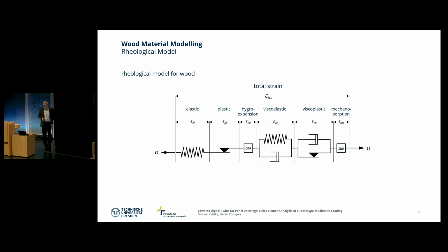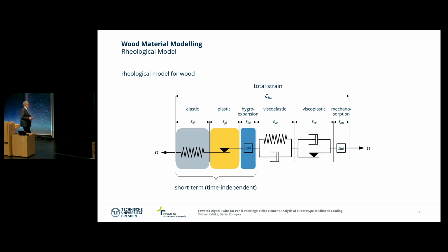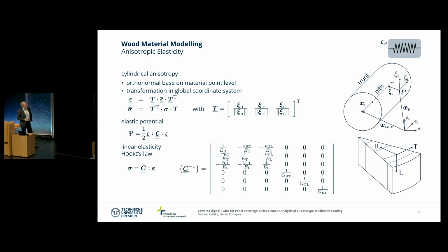So this is the material model we are going to use. We are developing stepwise. We have the elastic contribution, and when we load our material beyond the elastic regime, we have plasticity, irreversible features, we have hygroexpansion, and everything can be summed up as short-term response. We have the long-term response, on the other hand, which is the creeping, the different levels of creeping, so the linear and the nonlinear one, and we have mechanosorption as well, which is then altogether the long-term response of our material. So let's look into the different components stepwise.